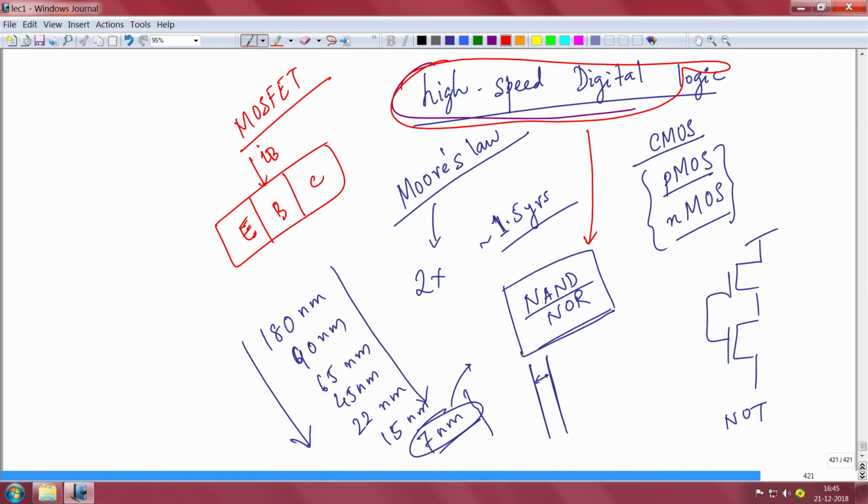You will actually keep losing power because of this base, but in a MOSFET you have this insulating gate. This is N plus, this is N plus, and then there is an oxide here. On top of that you have the gate metal. So this oxide has very little current leakage, so your input loss side, the current leakage, current loss, offset loss will be very low.